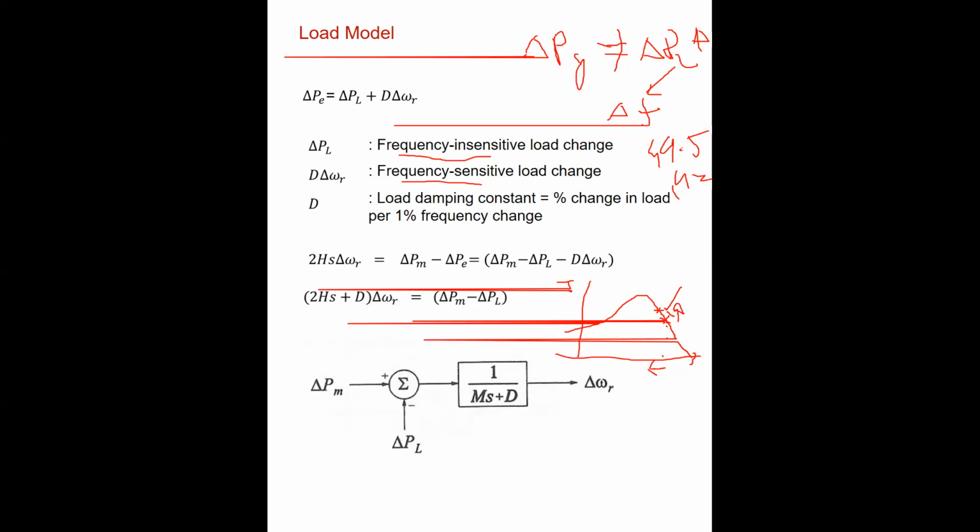And thus, this positive effect is applied on the generator here. And for the short duration there is a positive effect, and then the frequency may not dip further. It may not dip further. So the initial surge, the initial increase of the power or the developed torque in the system, is provided by the motor here.